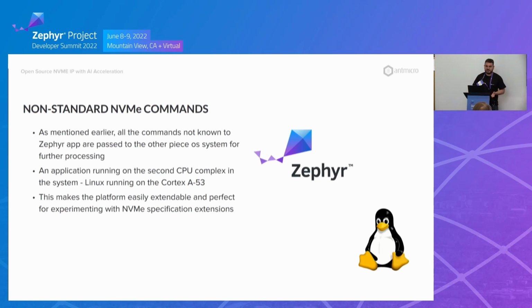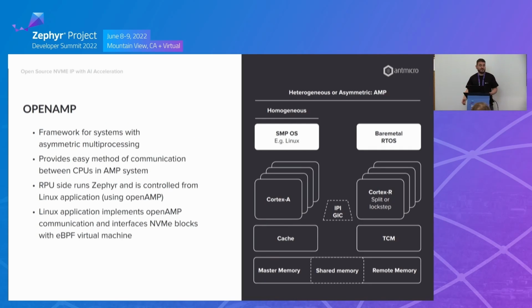Unfortunately, ARM is not RISC-V, but we're getting there. What if we can delegate everything? And we implement exactly that logic in Zephyr. So Zephyr basically handles all that it knows, and then if there is something that we don't know about, we can simply send it further. So how to do that? Fortunately, Zephyr comes with a pretty nice OpenAMP integration, so we could simply use it.